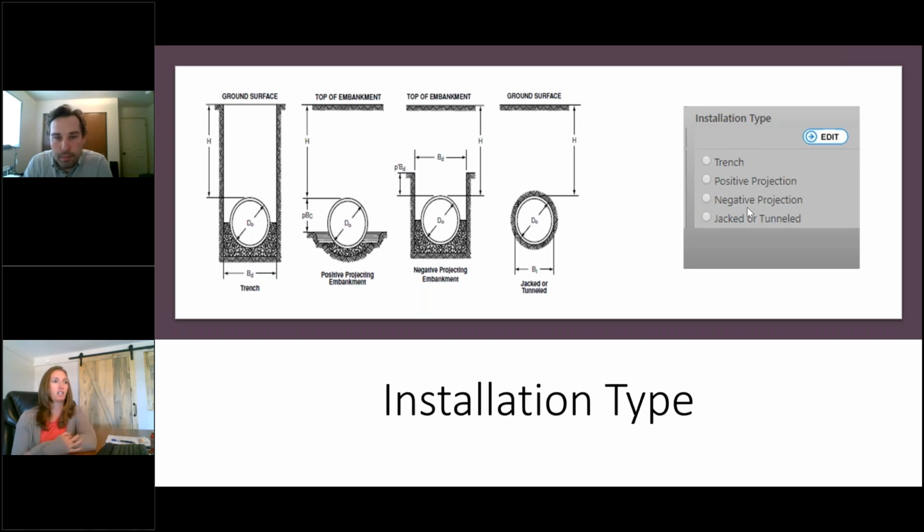When would you select to include or not include the fluid load in the analysis? That's a good question. The new AASHTO LRFD has you include fluid load. It really doesn't make that big of a difference in smaller diameter pipe. It's once you start getting to the larger diameter, where you're carrying a lot more fluid and it's increasing that load.